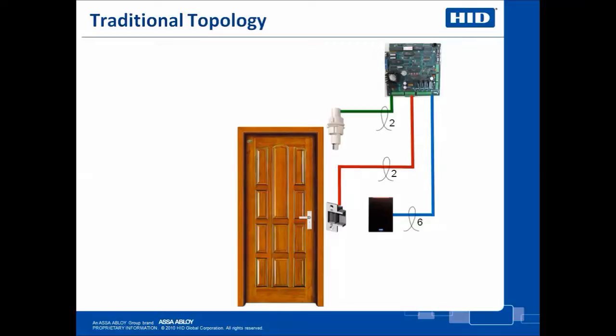door is securely closed. Most door switches are composed of 2 components: the immobile component that is inserted into the door frame and connected to the controller, and the second component, which is magnetic and moves with the door. A door being opened without a presentation of a card can be considered an off-normal condition known as a door forced open. Often, however, there is no reader on the secured side of the door.